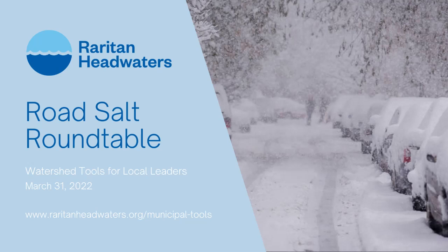Everything we're talking about is very, very difficult. But one of the things I always fall back on is, do you remember the days when liquids weren't really available? In cold temperatures you would use something called premix, which was solid sodium chloride, usually with solid calcium chloride flakes mixed in, very dusty. Eventually we got away from that, and if you were applying solid materials like sodium chloride to the road, you would pre-wet them with another product. It could be calcium chloride, magnesium chloride, or straight salt brine if you chose.